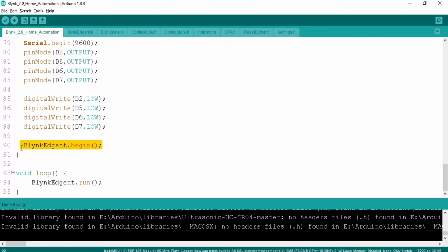The main work of this function is to set up your Wi-Fi board with the internet as well as the Blynk Cloud server, and once it's authenticated with Blynk Cloud, this device always automatically communicates with your Blynk app when powered up, because it stores all of your Wi-Fi credentials in your Wi-Fi board's EEPROM. In the loop function, there is just the Blynk.run function inside. The work of this function is just calling the virtual functions when any activity happens in the Blynk mobile app or web dashboard. All the processes are based on software interrupt.